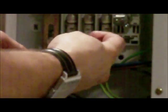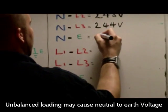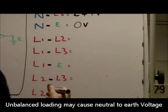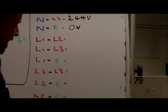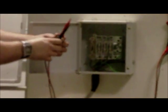Now between neutral and earth, effectively, we shouldn't get any kind of voltage there, which is good, because neither of these conductors are a line conductor. The neutral is considered to be a live conductor, but it's not a line conductor, so we've got 0 volts, and I'm happy with that. If you had a voltage there, it can be down to poor power factor within an installation, causing the neutral to carry excess current.